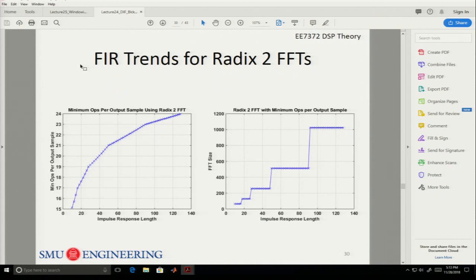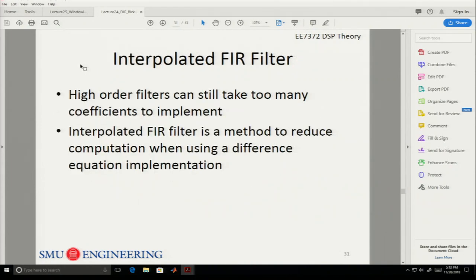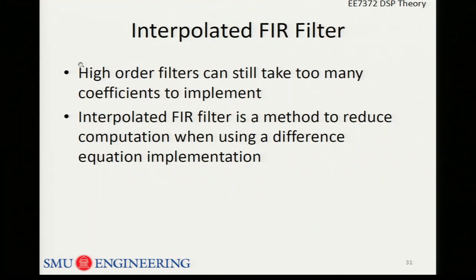So that brings us to our next topic here, which is the interpolated FIR filter. Now, all the stuff I said before was, okay, that's great if you have an FFT, but what if you don't? What if all you've got is digital logic that you're programming in some way with a programmable logic device or something very simple, and you really don't have an FFT-like engine, and you don't have the resources to even code one up inside the amount of logic you have, or you're limited in some way like that.